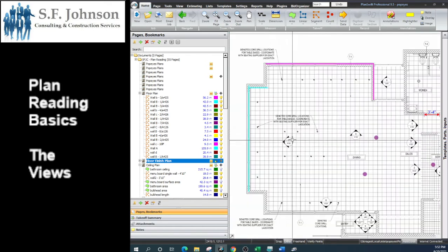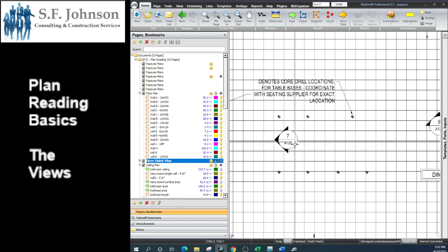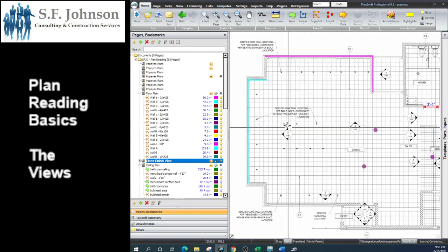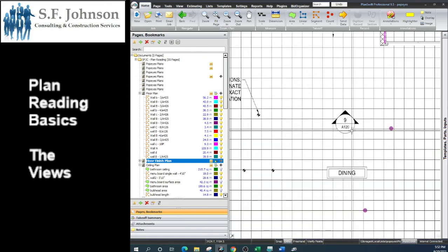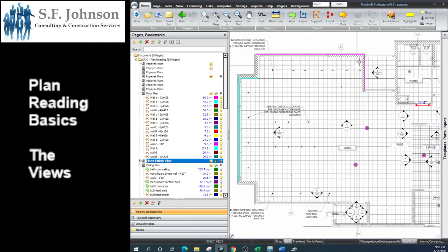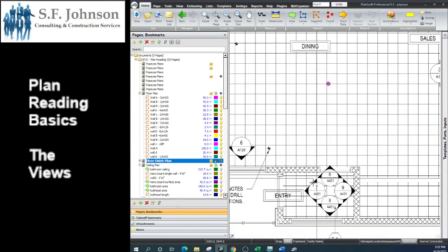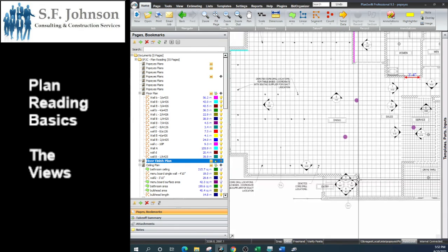And so what it's telling us is that if we go to image number 7 over at page A120, we're going to see all the finishes that's here on this wall. If we go to image 9 over A120, we'll see all the finishes here and all the way around. And here, you always want to see elevation markers. So this is an interior. These are interior elevation markers, are what they're called.